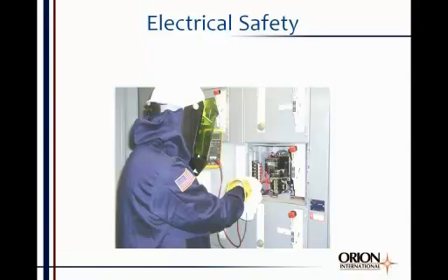He has on arc-rated clothing, that's that blue suit he's wearing. He has an arc-rated face shield, so that if an arc flash were to occur, his face wouldn't get burned up. He has on a plastic hard hat, safety glasses, earplugs, and protection for the back of his head, in this case a hood. This is the typical dress in industry now for doing voltage testing in a motor starter.